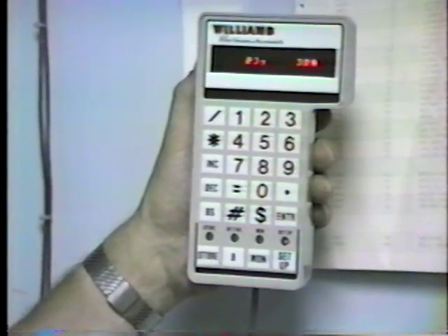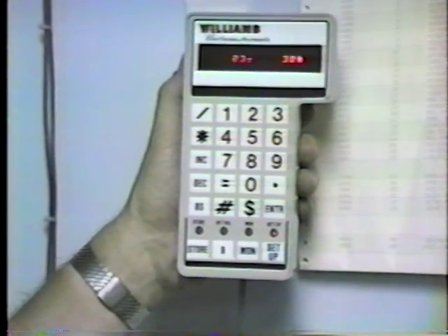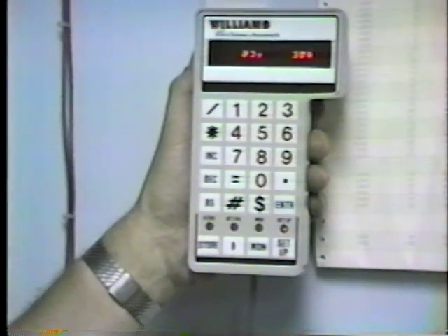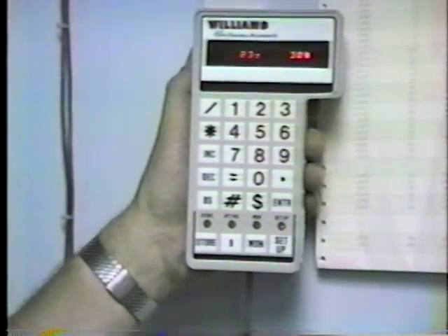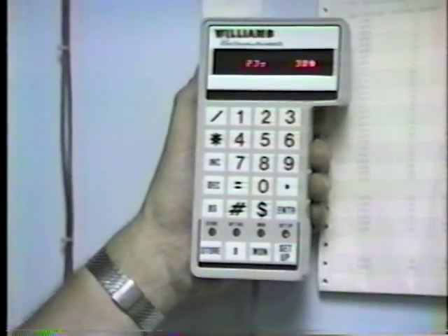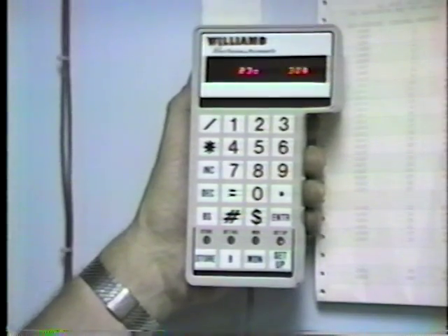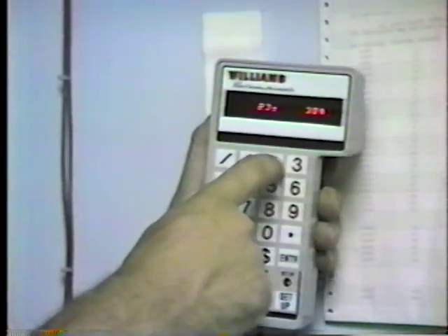Now, there is going to be another factor which indicates that we will not begin counting this time until we're certain delta pressure is below our target. And what number is that? That's number 26. It's called the low delta pressure startup time. Let's go look at that and then we'll come back.